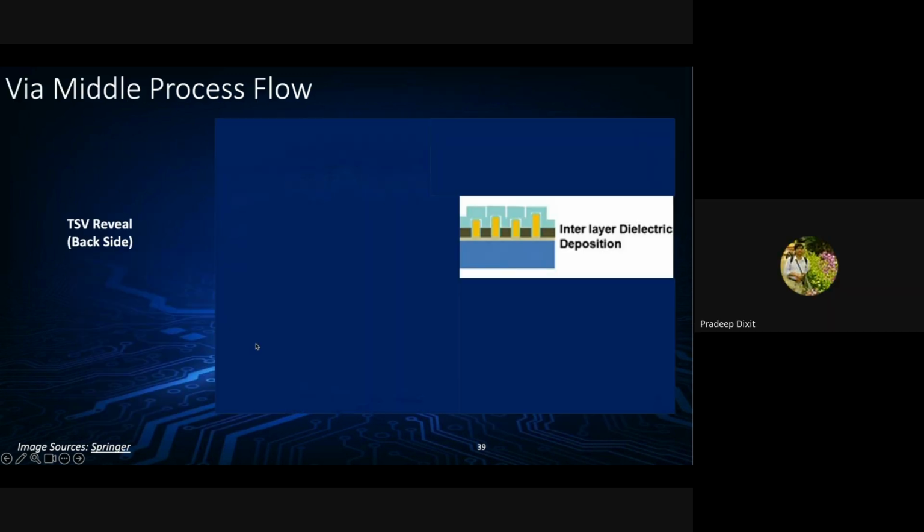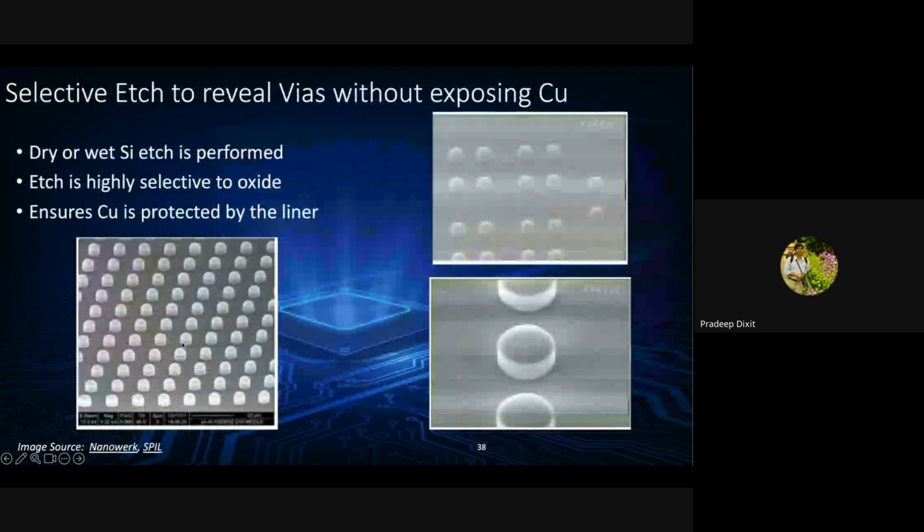So Uday, just one question on the previous slide. As we know, for example, this SF6 based plasma always has some kind of a uniformity issue from the wafer edge to center, especially on a 300 millimeter platform. Even if we consider, let's say, 1% uniformity, it is always going to have something about 5 to 7 micrometers of difference. So how does the industry compensate for that variation?